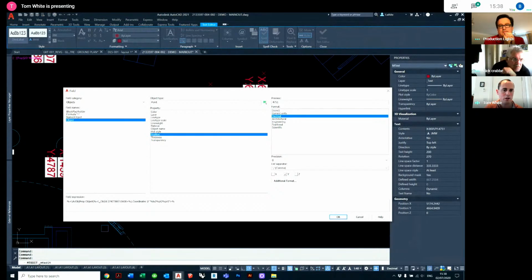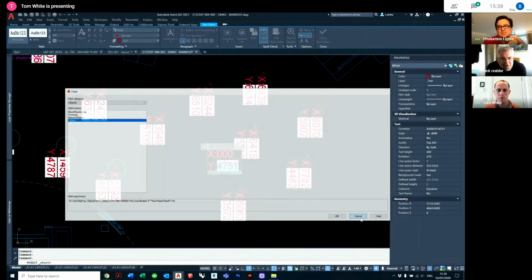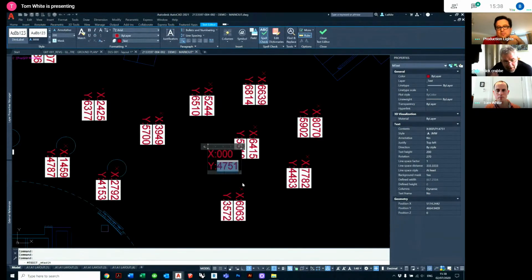Sorry, I was pointing to the screen, but nobody can see my finger. I've got object, it's got position, it's got decimal, and in this circumstance it's the Y position that I've ticked. And I've got a precision of 0, so it's easy to read. So in this circumstance, it doesn't actually matter that it could be 4787.001. I just want to know it's 4.7 meters away. That's something that I might actually use, and we're back to loudspeakers or lights on a truss, the mark out thereof.